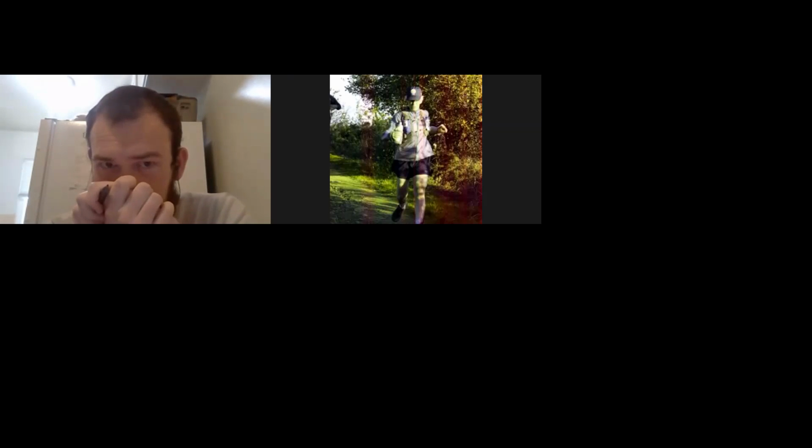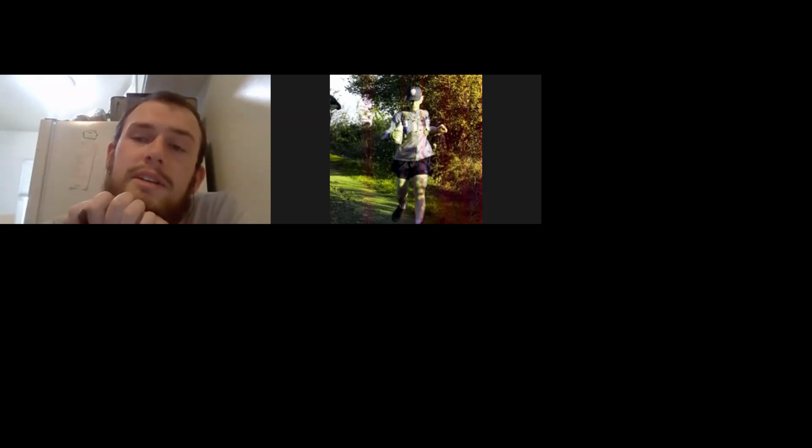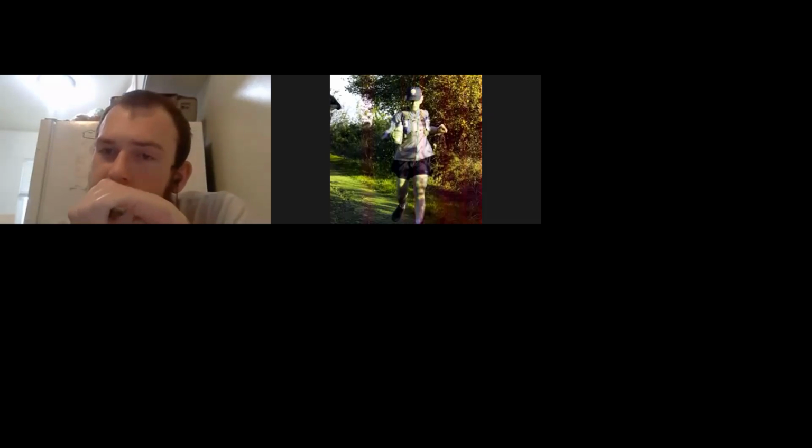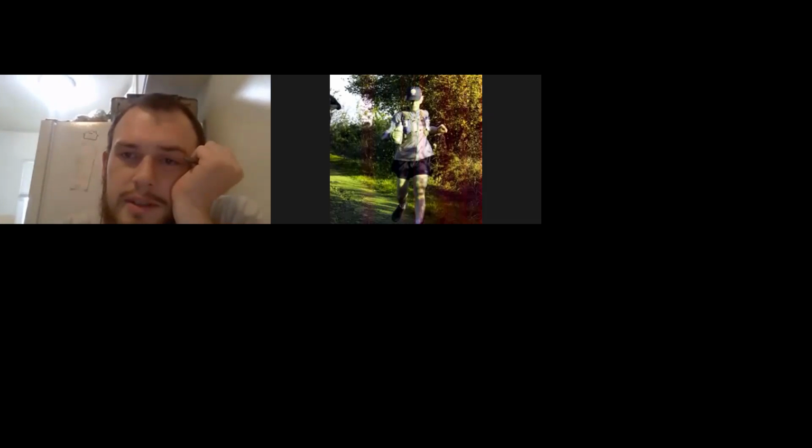But so it looks like for the output stage, Q5, Q6, Q7, and Q13 make a push-pull output similar to what we saw in the last example.